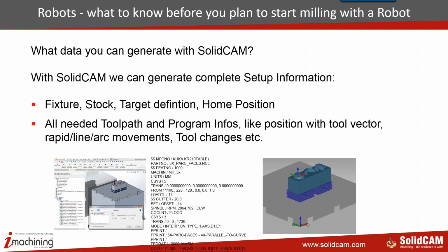So what data can you generate with SolidCAM? With SolidCAM, we can generate the complete setup information for the robot. We have fixture, stock, target definition, home positions, all needed toolpath information, program info like position and tool vector, rapid lines, arc movements, tool changes, etc.